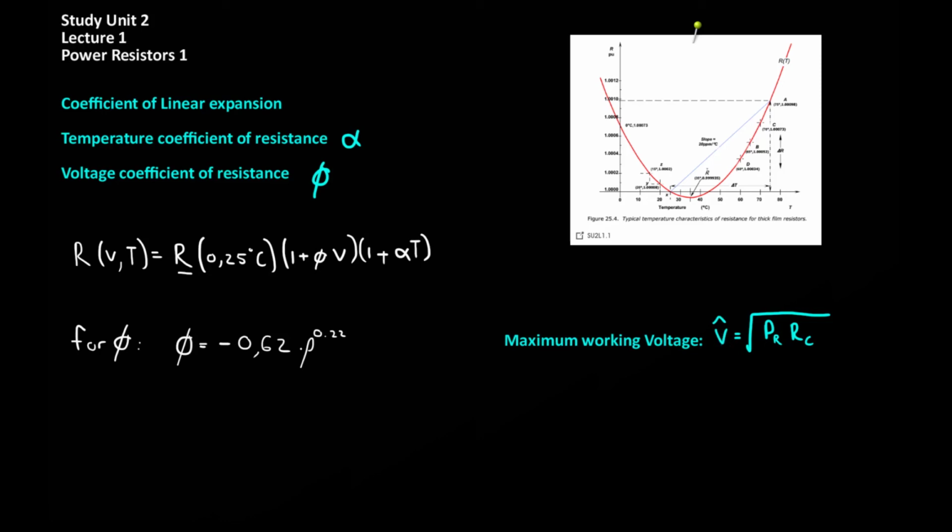Finally, a resistor will have what is termed a residual capacitance and a residual inductance. The residual inductance will increase as both the resistance and the power rating of the resistor increase, whereas the residual capacitance of a resistor will increase as the pulse rating of the resistor increases.